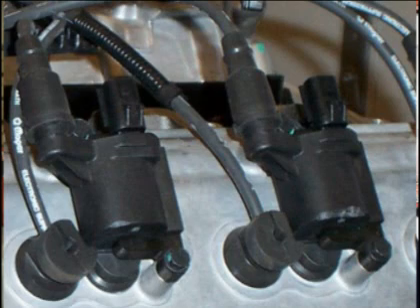After reading the codes and procedures, it will become clear that it will take some understanding of a new ignition system test. The ignition system is not a new system. The components are the same, with the exception of the spark plugs having a new heat range. It is a direct ignition system. The coil pack we are familiar with, the short plug wires, one power wire and two trigger wires go into the coil. The powertrain control module is still in control of the ignition system.